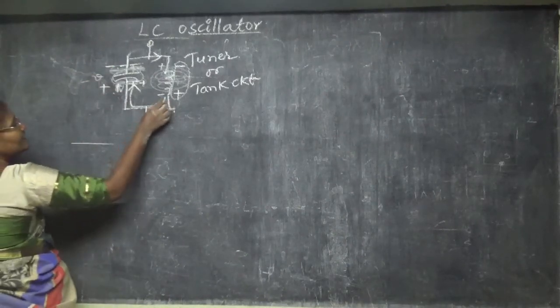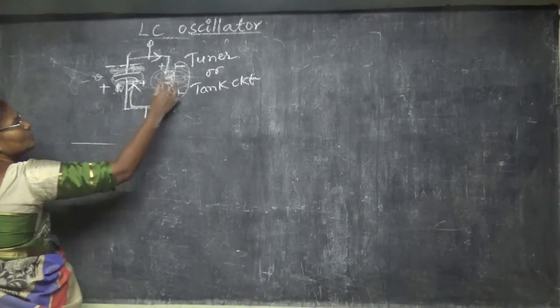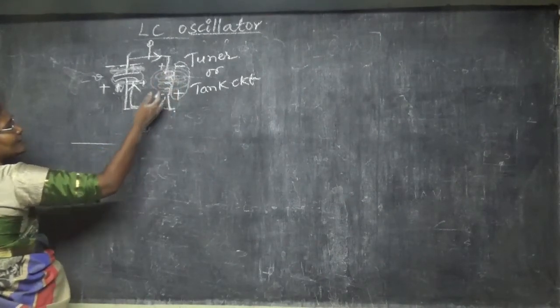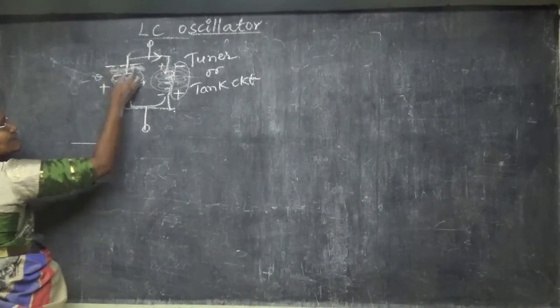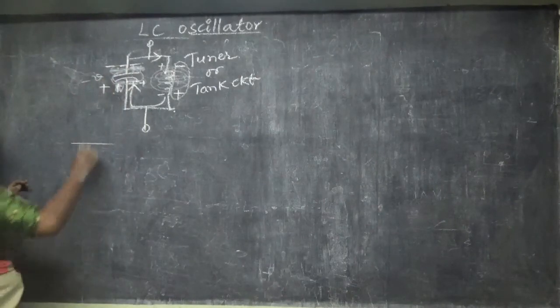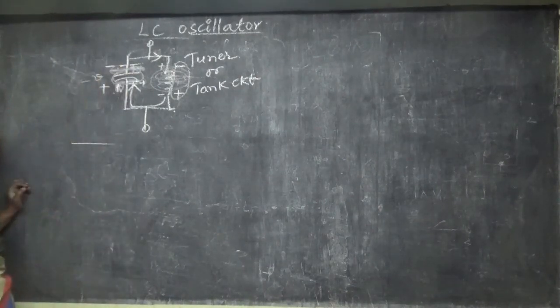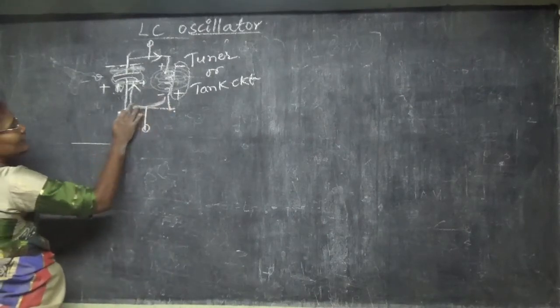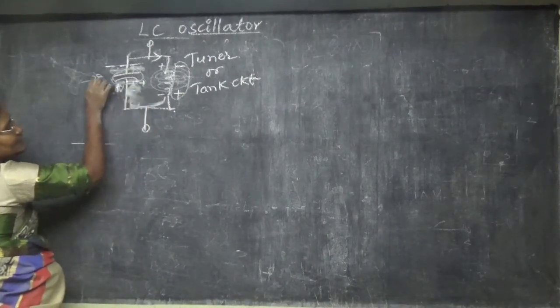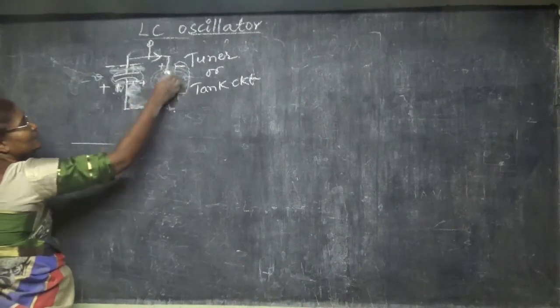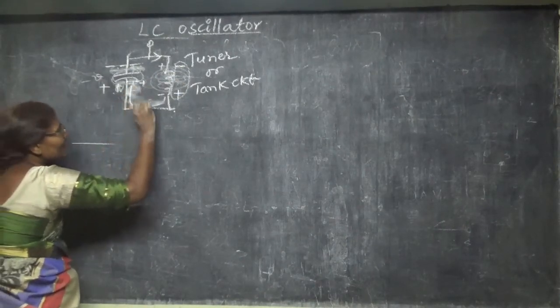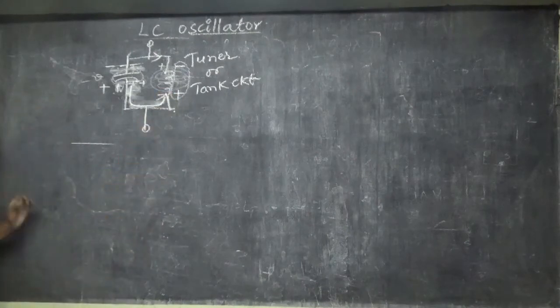So in this reverse direction, the total magnetic field energy will be converted into electric field energy. So it will be charged fully to the negative volts. After it is charged to negative volts, what happens? Again the current will now, this has fully charged, and that has become empty. Now my current will start flowing in this direction. So how can I explain this?